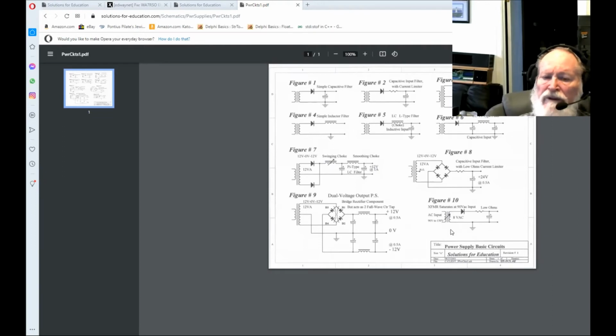People bought these. They knew what they did, but they didn't know how they worked, and they couldn't care less. They said, hey, I put in a brown-out power supply, I will have a nice constant voltage, and I'm happy, so I'm willing to pay extra money for it. And that's what they're known as. If you go out on the web and look them up, you'll find they're listed as brown-out power supplies. What they are is a new version of this transformer right here. They are, in fact, a Saturable Reactor transformer.